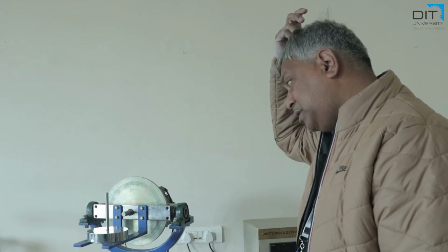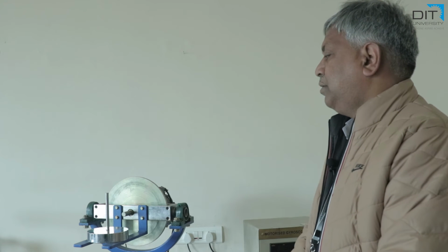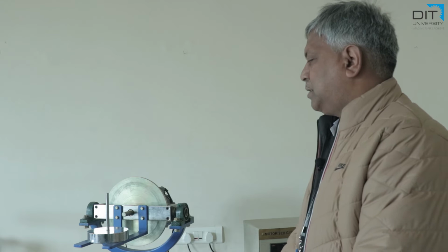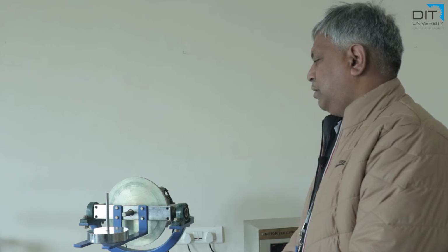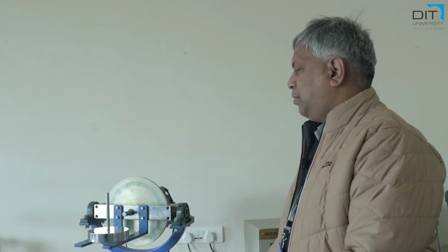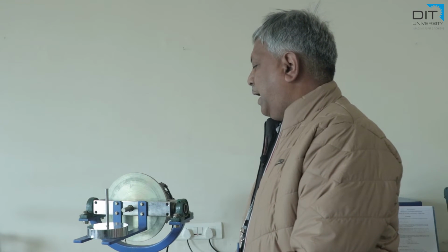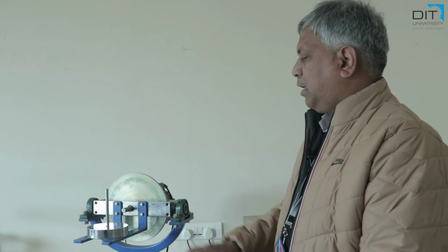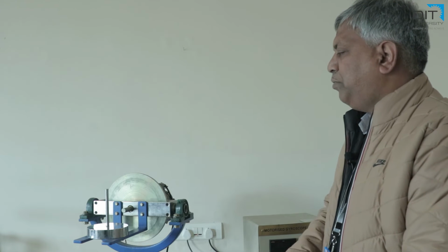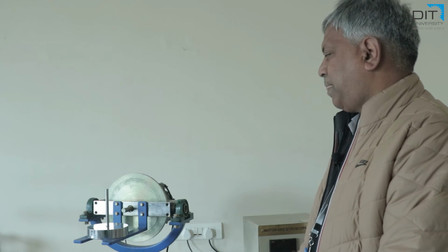And the density of steel, must remember that it is 7.85 grams per cubic centimeter. So this way, if you calculate, we find the weight comes as around 4 kilogram, right? That is one important thing. And once the mass is known, radius is known, the moment of inertia can be calculated. So that part would be a constant for our experiment, right?